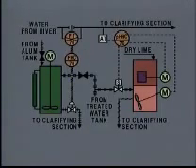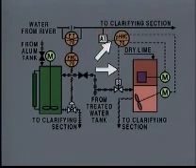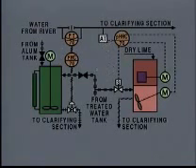A control system starts and stops the lime system based on the pH of the raw water from the river. The control system has an analyzer transmitter that measures the pH of the river water. As you see here, this type of transmitter is sometimes represented by a square rather than by a circle. The dashed lines shown here are a common way of representing an electrical signal line. The transmitter sends an electrical signal to a pH recorder controller. The pH recorder controller records the pH of the raw river water.